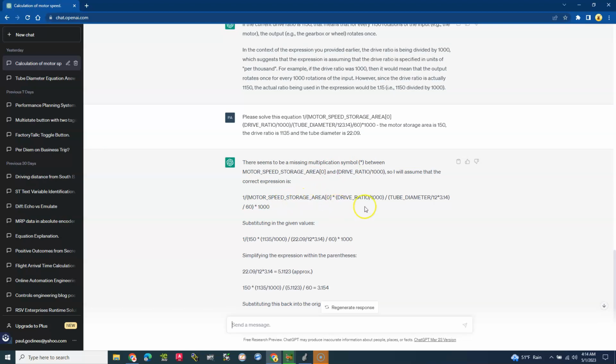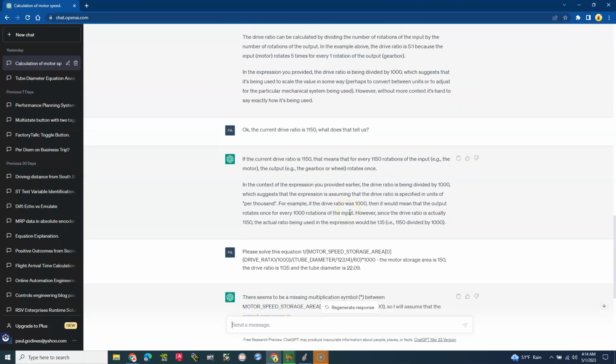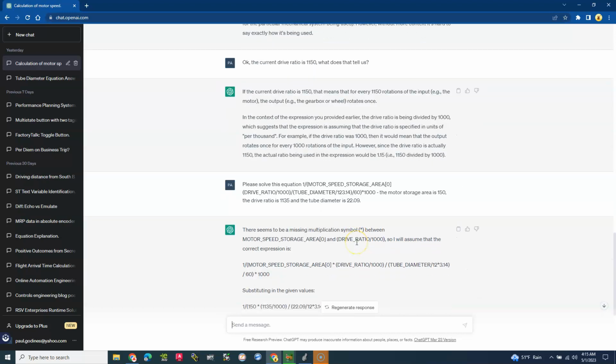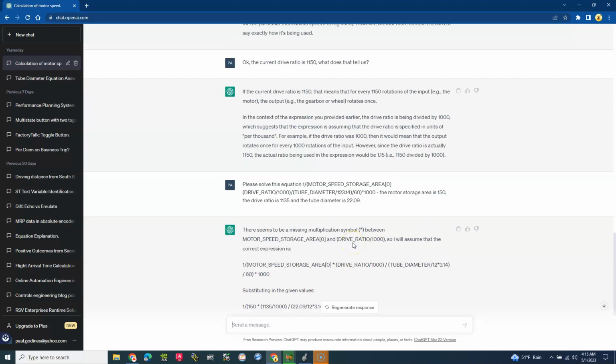We set the speed at 150. Drive ratio, we've already talked about what that is. We're trying to set a ratio that's equal between the two drives, so that the cylinders turn at a near identical ratio to each other, or we'll rip or bunch the paper. That's what our drive ratio is answering.